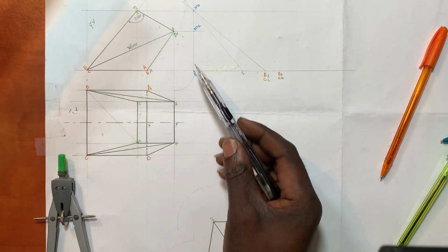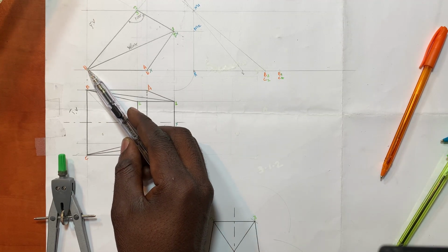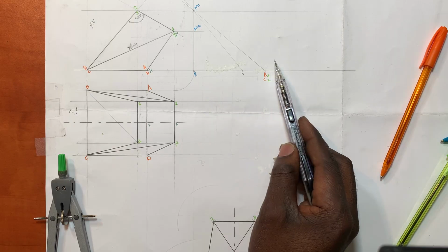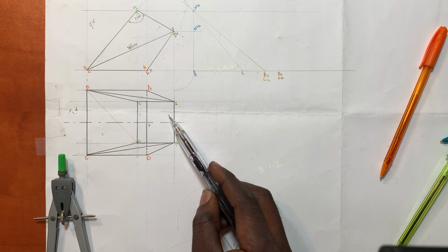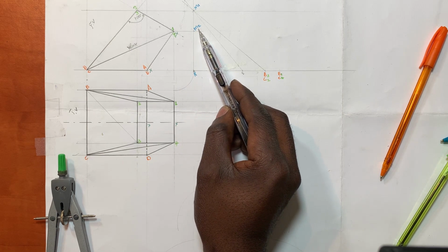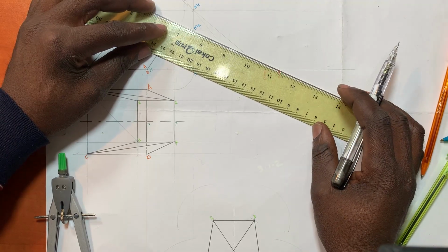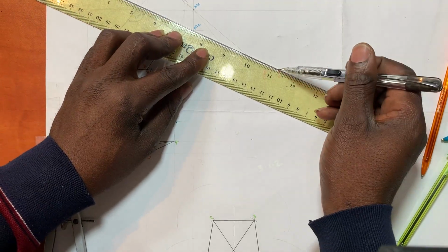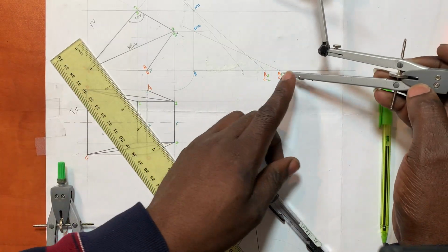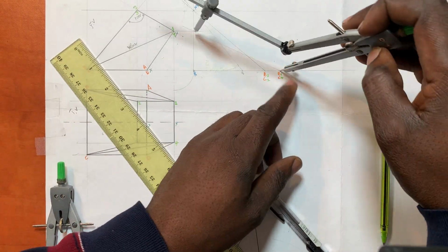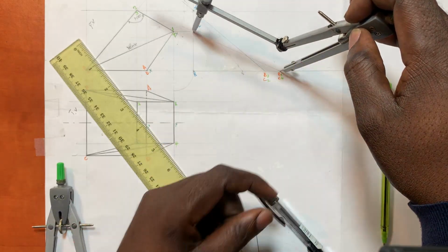Understand? So double check this one now. Which M number should I use? So this is B and the C, isn't it? Once it touches the bottom of your front view, it goes horizontal. So now being directed to 1 and being directed to 4, it goes up, up, up. Once it touches there, which means I have to use M2. So construct it to your M2. So there it goes. Understand? Then from there, place it here, M2. Just to repeat, further ascend to M2, which is this one.